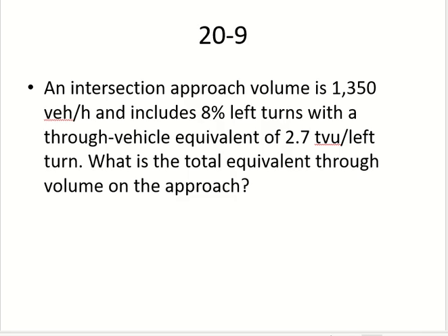They counted the total volume. And they found the percentage of left turning vehicles, like what you did in your term project. You found the percentage, right? So they did the same thing for the left turning. They found the percentage to be 8% left turning out of the 1,350 total vehicles. But the problem with this number is that those 8% left turning and the remaining are just added, which is wrong. Before adding, I need to bring them in equal terms, which is not done.